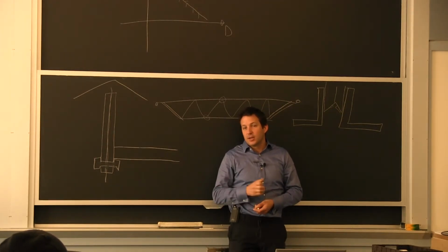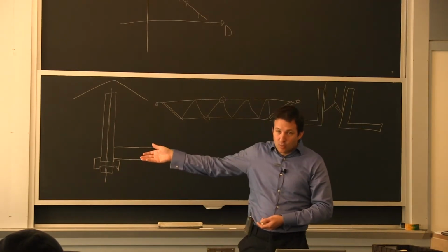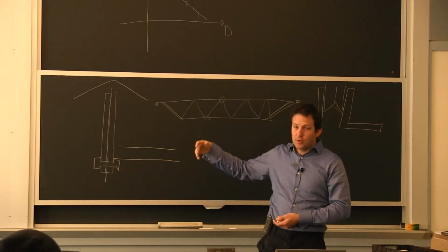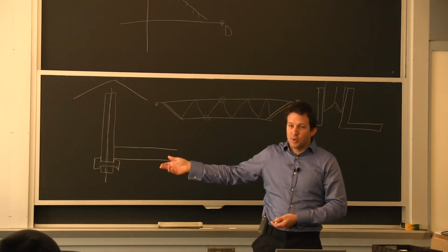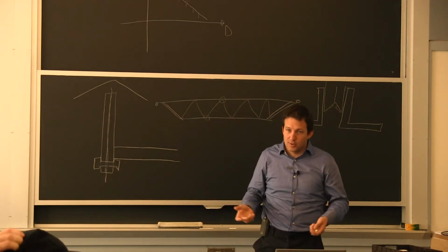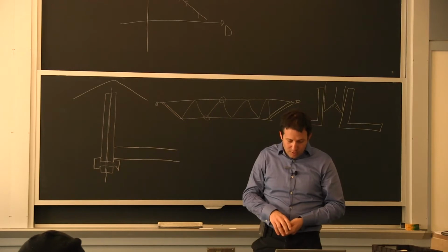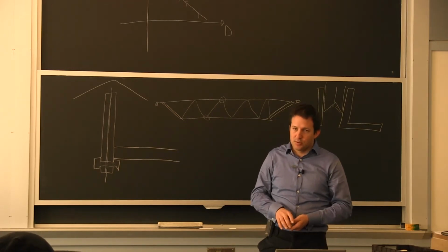Now, there's the other extreme. These are relatively thin wall, 1/8 of an inch. So if you come in straight polarity with a big electrode here, you can have burn through, and it doesn't look good. People don't like it. You have other issues. But in general, the tendency is for things to be done too fast.